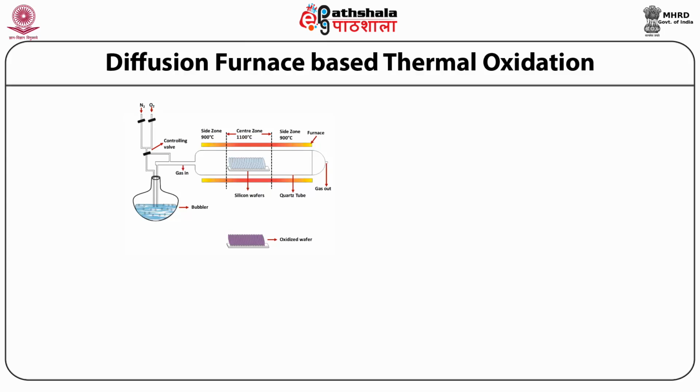So as the thickness of the oxidized layer increases, the diffusion of oxygen to the substrate becomes slower, leading to a parabolic relationship between the film thickness and oxidation time as shown in the figure below.